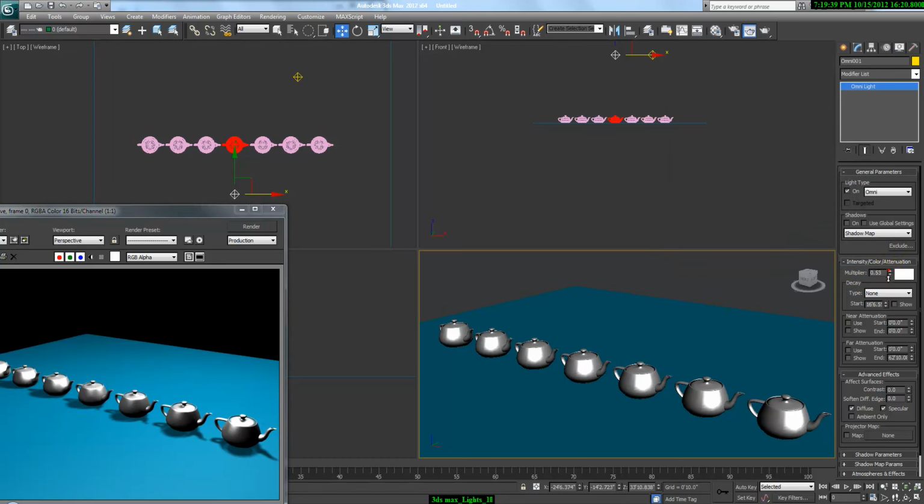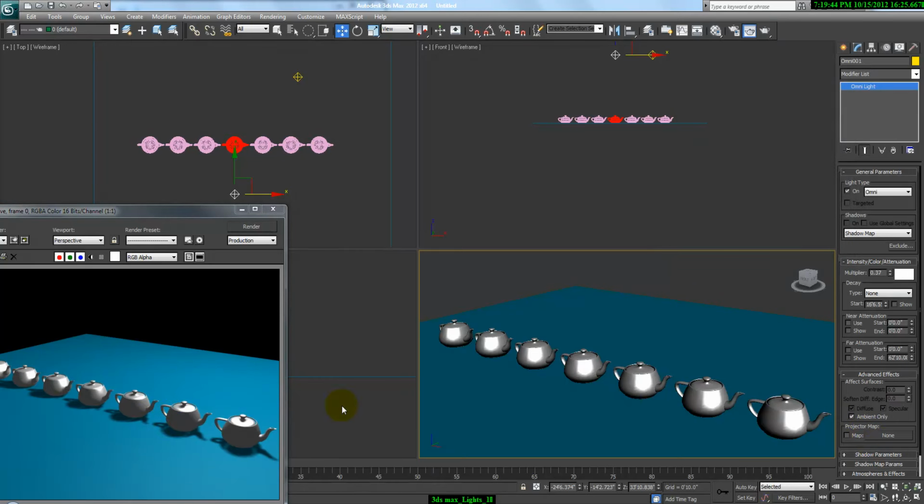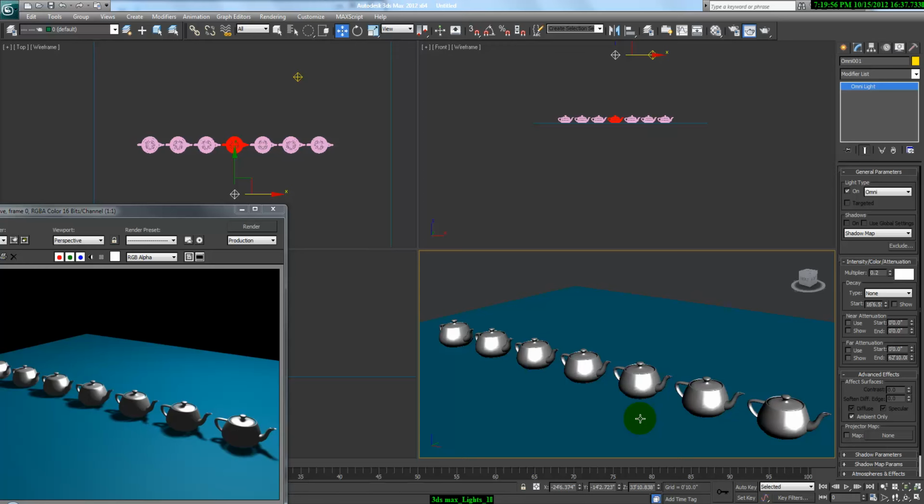और फिर उसका highlight और shadows दिखाएगा. Rather, ambience मतलब equal light bounce दिखाता है. Actually, when V-Ray or all these softwares are not used, the bounce light is where the ambience light comes from. But it has to be very minimum and has to be very much calculatively used. The plus point of this light is that it is very difficult, but it is one of the fastest rendering methods, and if you get control of this type of lighting, it's very good because you can create a very good scene in a very small amount of time.